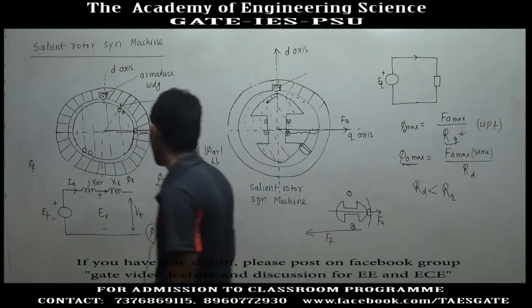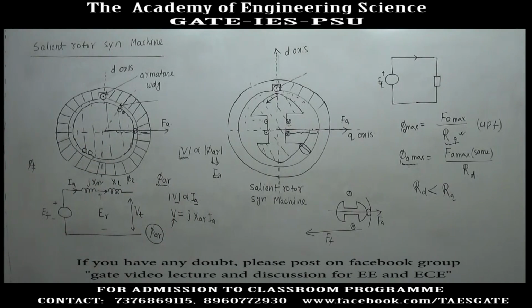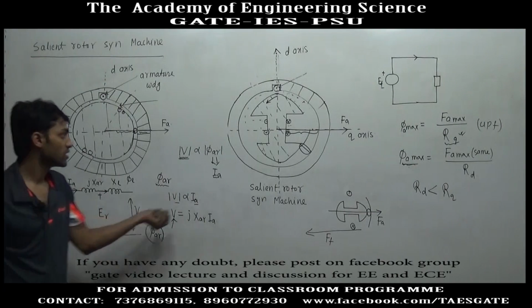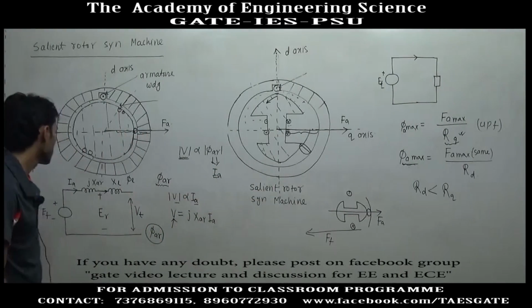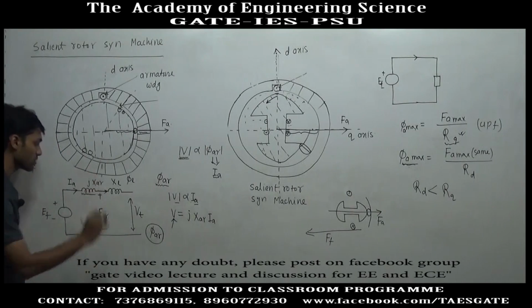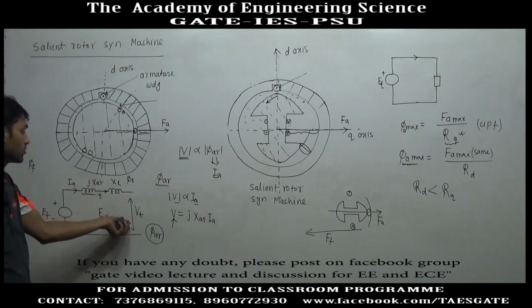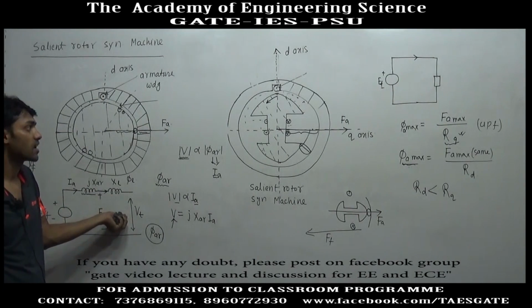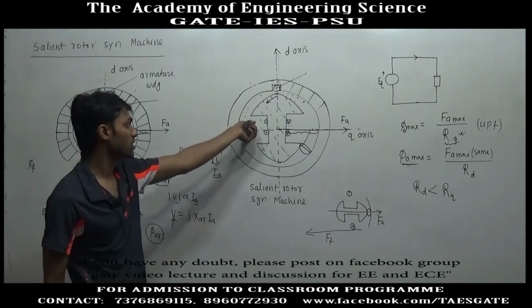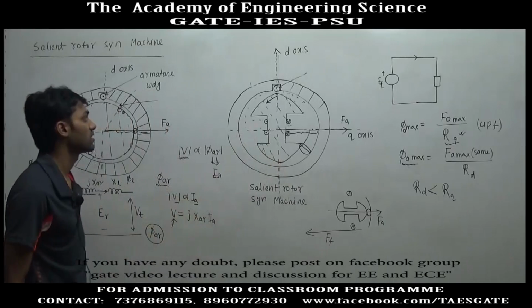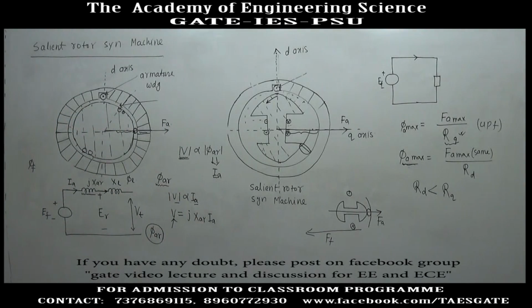The circuit diagram of synchronous generator is fixed irrespective of the power factor of load, but here flux depends upon the power factor. So, this reactance will depend upon the power factor. So, the same circuit is not applied, and there may be infinite types of load. For different load the power factor angle will be different. So, the number of positions of rotor relative to the maximum armature MMF will be infinite.